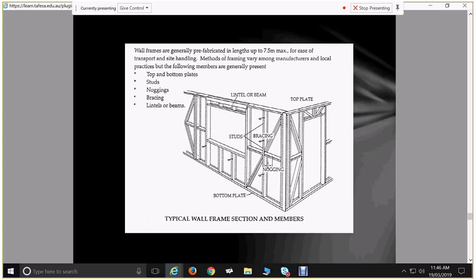One issue that happened with steel frames really early in their design and manufacture is that a lot of plumbers were just running pipe work, so you've got your steel frame stud in a C shape, and they'll just run their pipe work in that steel stud. And then the plasterboard fixers come along using screw fixings, they screw into the stud and straight into the pipe work. But because a lot of that pipe work is this PEX material, your screws will go into it and it won't leak. Because it's that malleable sort of plastic material, screws will go into it. And that'll be fine for 5-10 years until that screw ends up rusting out, and then there's water in your wall and nobody understands why until they pull it apart.